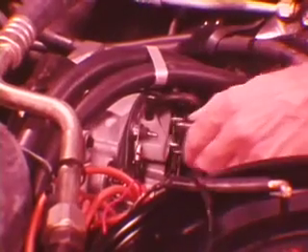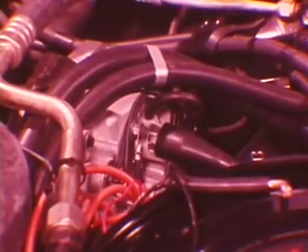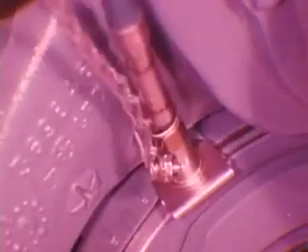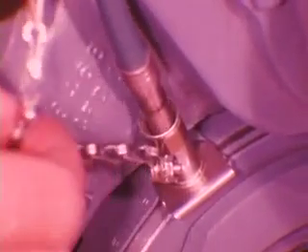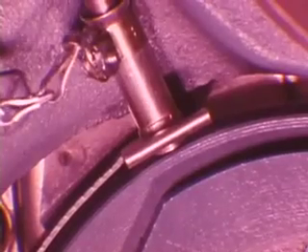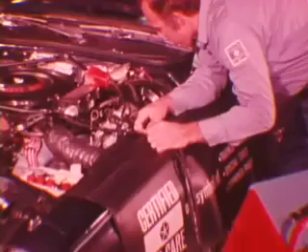Connect the analyzer black lead to a good engine ground, such as the alternator ground terminal. Attach the magnetic timing probe clip to the engine timing indicator plate and insert the probe into the clip until it fully bottoms out on the vibration damper. Plug the power line into an AC outlet with a grounded third wire. Turn on the power switch and check the computer test code.